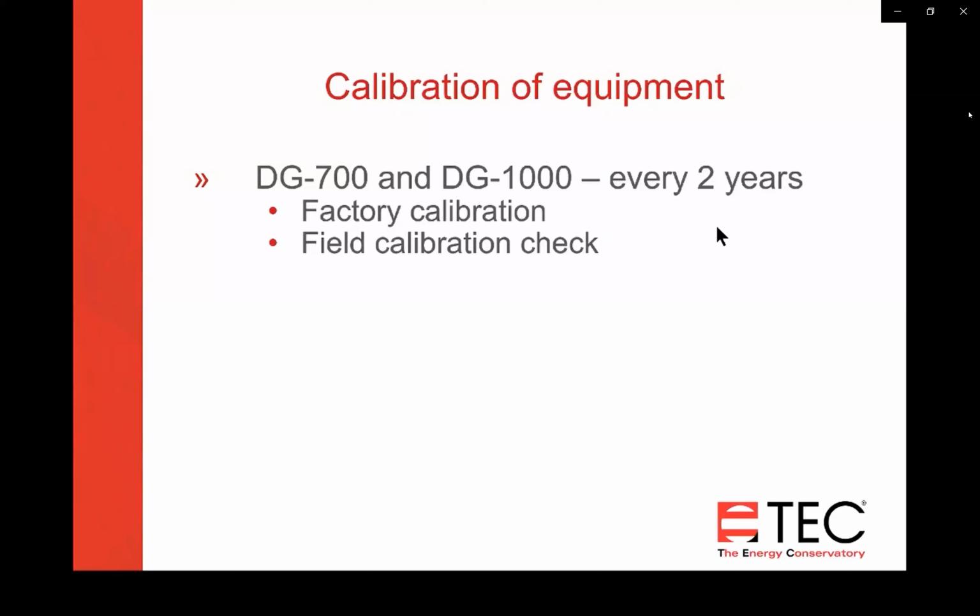So you'll see on the graph that the two gauges that are being compared, that one of them has been calibrated recently, and that's the one you're comparing to. So it's helpful to use that extra level of quality control. So you've got a documented test that shows the calibration for all those gauges.